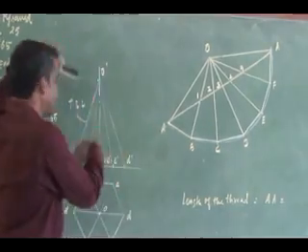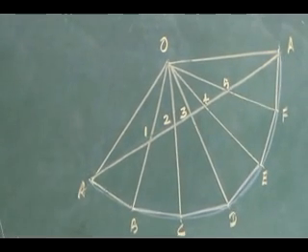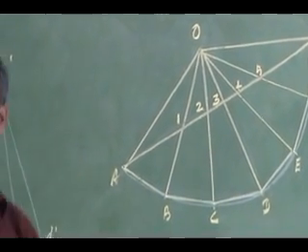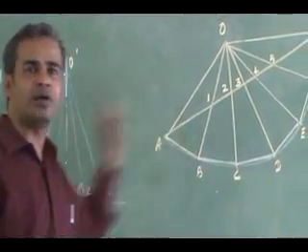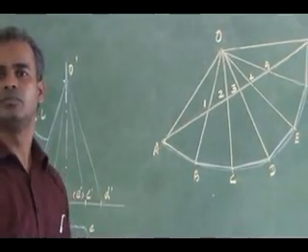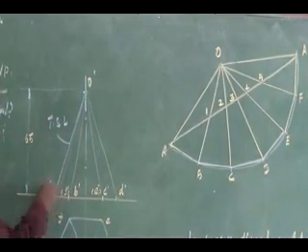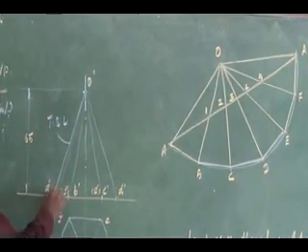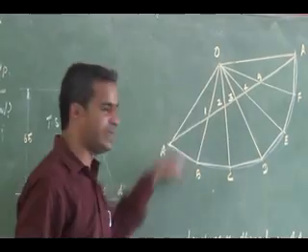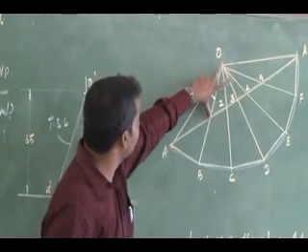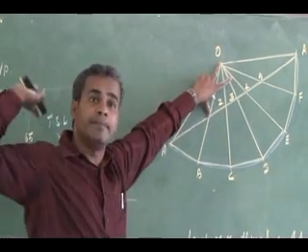These cutting points I have to transfer to my front view, something like a cutting plane. Connecting those cutting points is nothing but the representation of the thread in your front view. So how can I go back to my view from here? I just have to measure. My thread starts from A, so in my projection it is also going to start from A. Then cutting point 1 is on its slant edge B. So I have to measure this distance and transfer it to the measuring line.